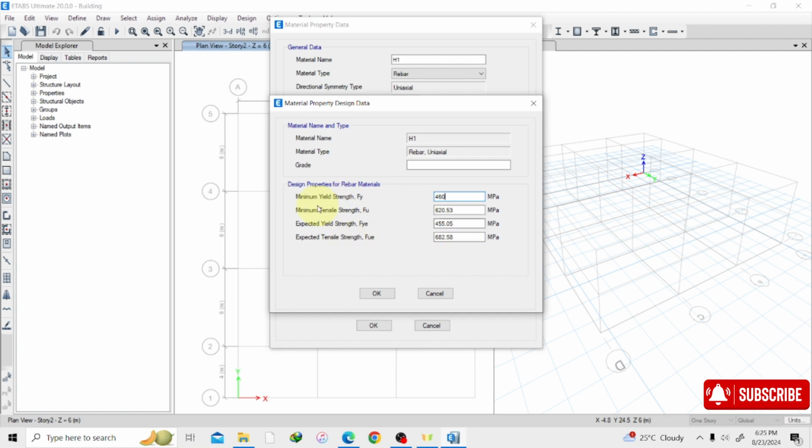These are just values we'll be multiplying. So we'll be multiplying our minimum yield strength with some modifiers. We are just going to modify this value and input the values here. Our minimum tensile strength is 1.5, so I'm just going to input the formula inside the bar and get my straightforward answer. So 1.5 times 460. The 460 is my minimum yield strength. These are just modifiers I'll be multiplying to get these various parameters. So it's 1.5 times this minimum yield strength, and I'll just tap enter and I have my value.